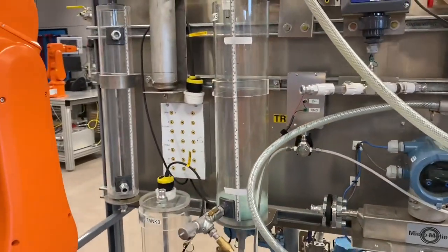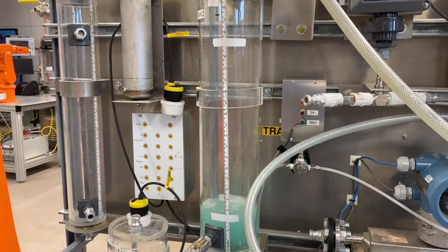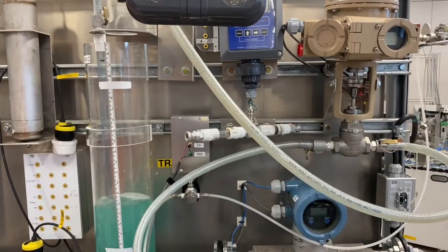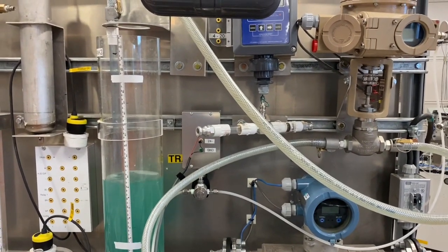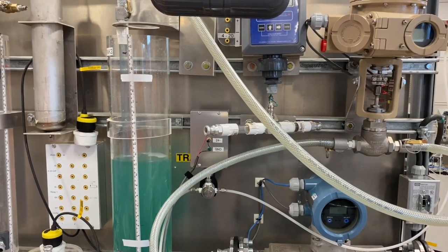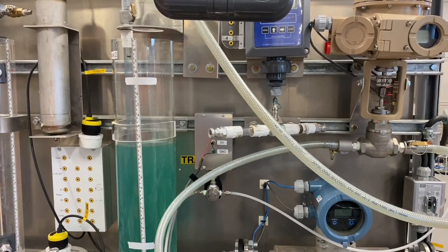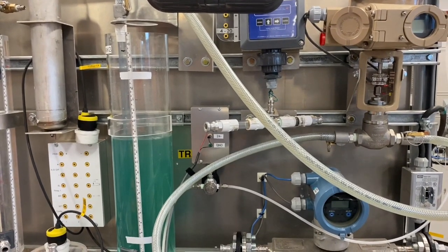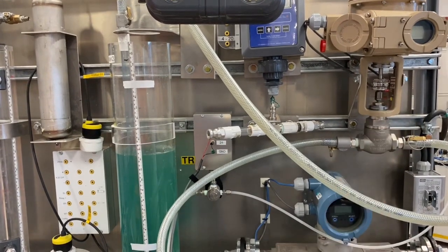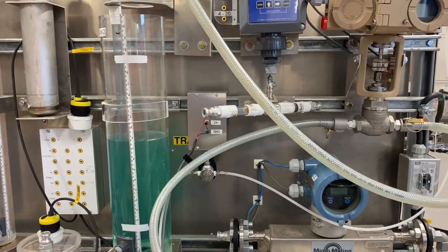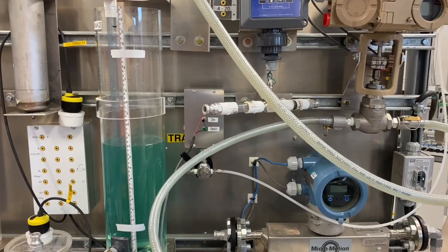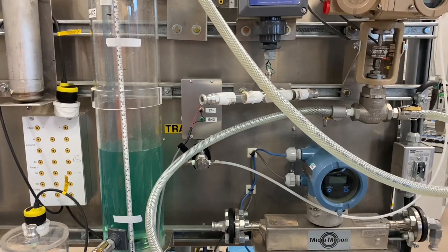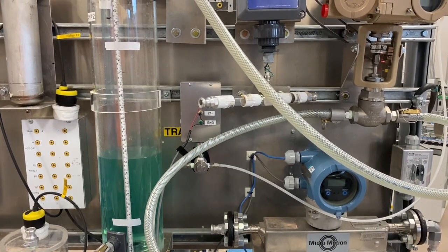and there you can see the vessel is starting to fill. So in the program, I have it written to shut the valve. Our valve over here should shut when we get to approximately 60% full in our vessel. So the analog input there, so it shut off, and now it's letting it drain. And if we watch over here, we should see our valve open again at approximately 40%. So those are our 2 trip points: 40% when the level's dropping, and 60% to shut the valve, to stop the level from rising too high.